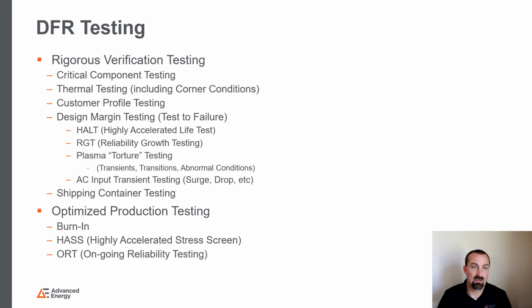I want to briefly touch on DfR testing as part of our DfR process. Ultimately, we want to find and fix as many failures as early as we can by analysis, but testing still plays an important role. One important thing we can do with testing is before we even put a component into a design, we can subject it to component level testing, looking for specific failure modes of the device so that we're ready to use that device in the design. We also want to verify through our testing that we didn't miss anything, that we meet our internal derating guidelines, that we understand what our margins are on the design.